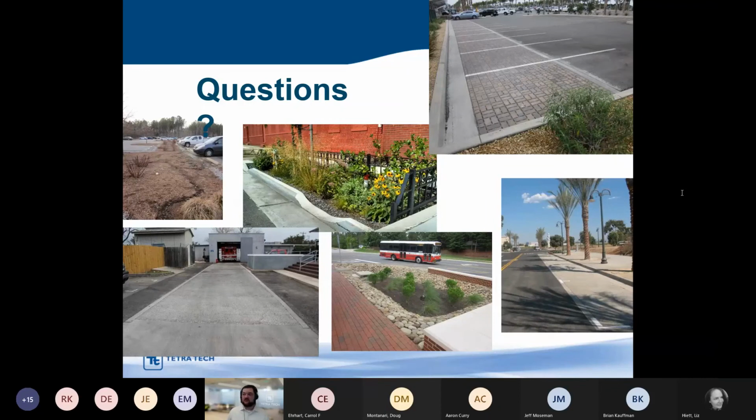I know specifically of a permeable pavement site that was put in while I was an extension associate at NC State. It was put in 2005, and it has been maintained. They've been sweeping it fairly regularly, at least once a year, and it's still functioning. I know there are permeable pavement sites in Florida and other areas that have been in for 20 to 30 years and are still holding up structurally, but they are regularly maintained.